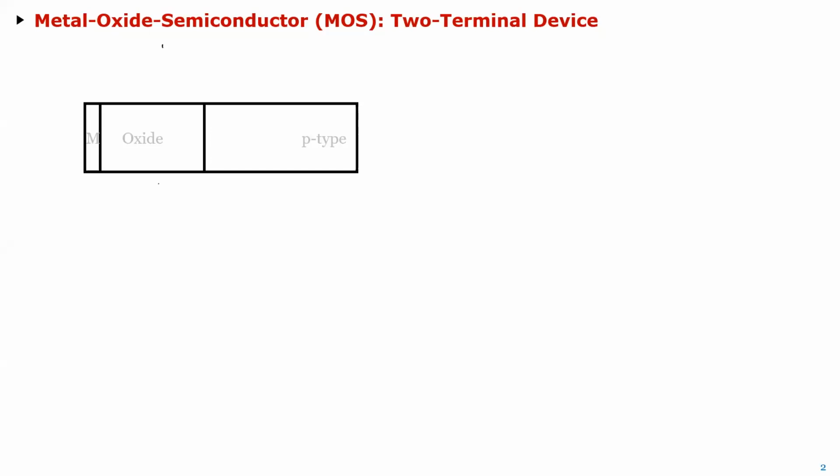And so that's how we said, okay, let's look at a MOS device, just the MOS sandwich, metal, oxide and a P-type, and see how we can control a channel through the voltage, and then we'll see how to conduct current through it after that. So we'll just look at the channel formation, which I quickly went through. We'll also quickly go through it again, and we'll quickly go through it again next time.